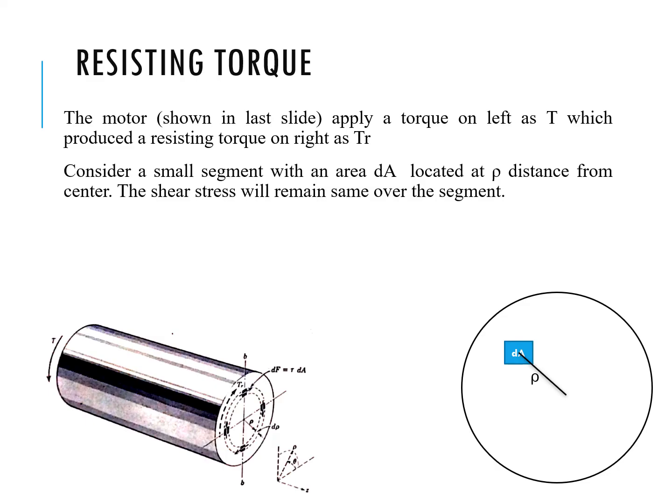Because we are studying torsional loading, in this type of loading only shear stress and strain are important. As we have already studied axial loading, in axial loading normal stress and normal strain are important. Here shear stress and shear strain are important, and also the modulus of rigidity is important. So our discussion will only be on shearing stress, shearing strain, etc. So this is a segment.